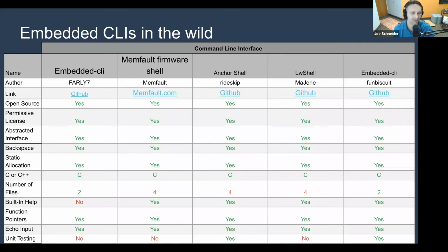We were hired in the not too distant past to do a security audit of an IoT home product. And on that product, it was even spelled out what to do, right? There are some typical security things you do, like blow the JTAG access fuse, so nobody can JTAG into it later. But one of the things right on the line item was disable the UART. And in this case, they wanted the UART disabled, but it was wide open.